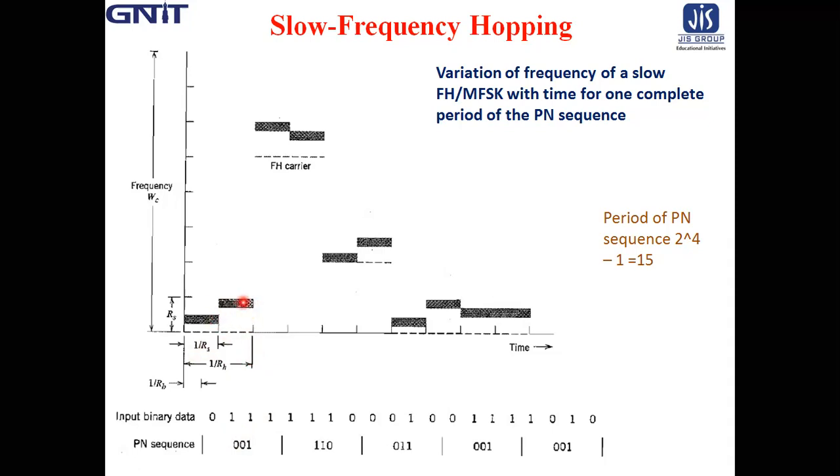So this is for 1 frequency. In all the cases, these two are slightly different, but here it is the same. Because see, in the last 4 cases, 1 0 1 0, same code, 1 0 for the first 2 bits and second 2 bits is 1 0, and the PN sequence is the same, that is 0 0 1, that is why it is the same.